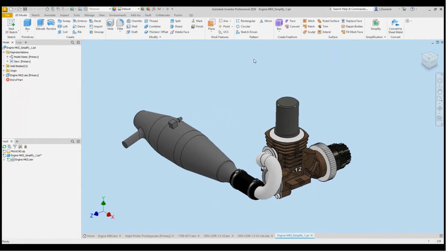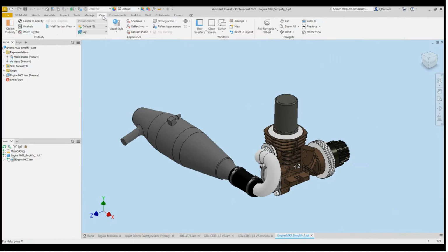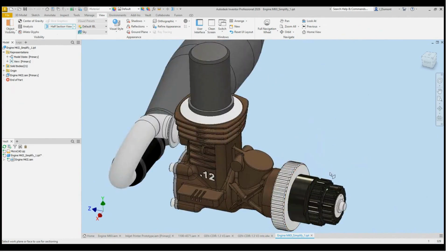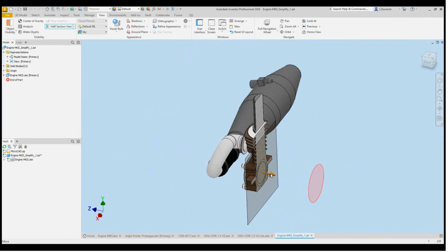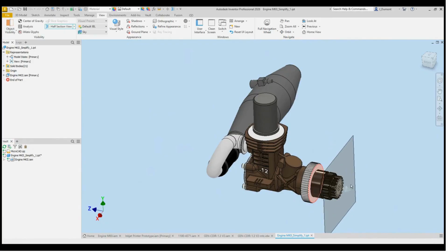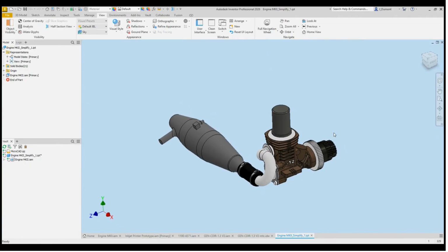That is very simplified. And there's only one component, but there's 329 solid bodies. And so now if I section it, let's go here this time. All the voids are filled, all the components are gone that are inside, and it makes the assembly or part file a lot easier to manage. So make use of the simplify command. I'm finding a lot of need for that today.